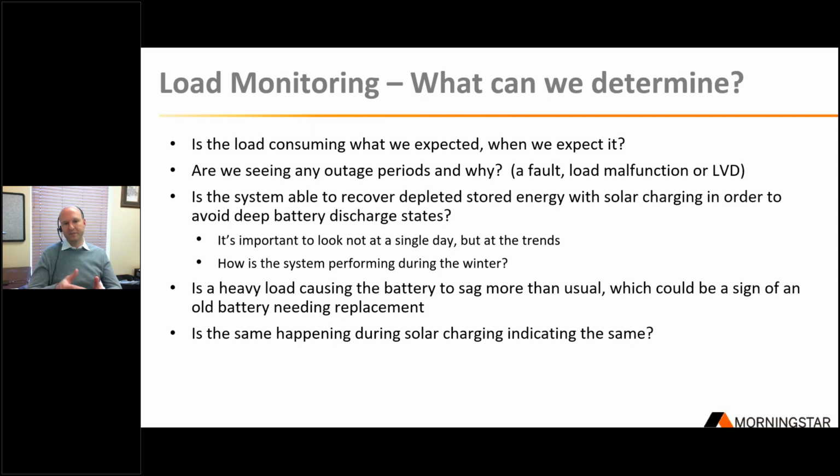And is the system able to recover from its depleted state? In other words, if you see that your battery is no longer going into absorption, but it's staying in bulk every single day, that's going to cause long-term sulfation and battery damage.